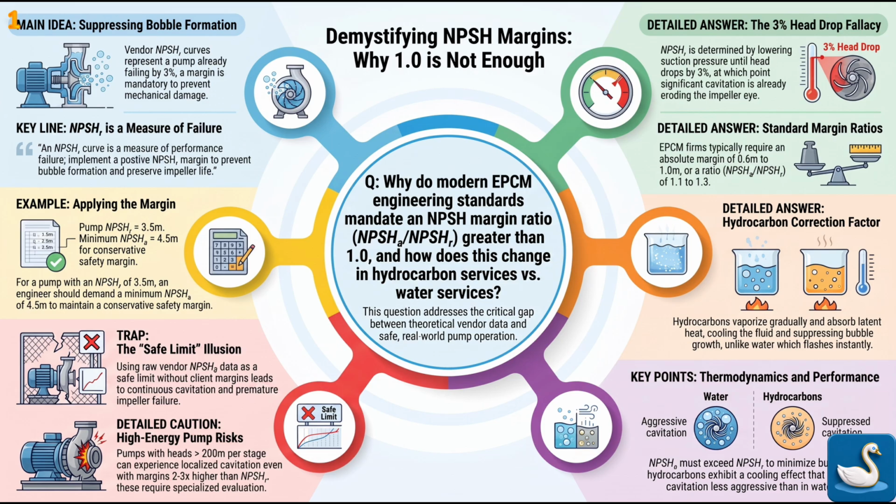So a full meter of margin. Yes. An NPSHR curve is a measure of performance failure. You implement a positive NPSH margin to prevent bubble formation and preserve impeller life. That is the fundamental rule. That covers standard pure water.